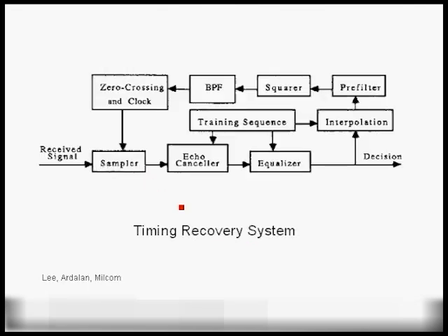This is also on the same paper, where we're showing the received signal being sampled, and we actually have a timing recovery loop in which the signal is resampled again at different time phases. We go through an echo canceller and equalizer, and we get the decisions. This again illustrates the fact that we support timing recovery, feedback, and joint, for example, echo cancellation and equalization in a Capsim simulation.